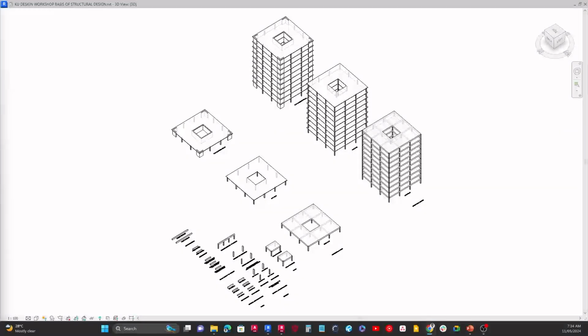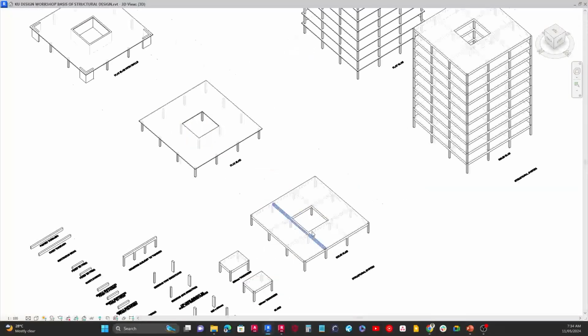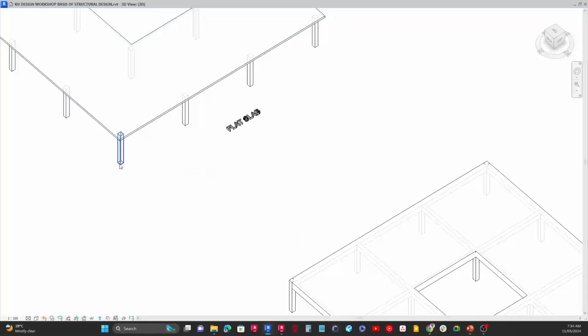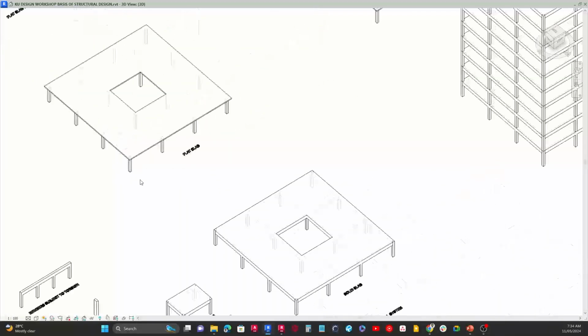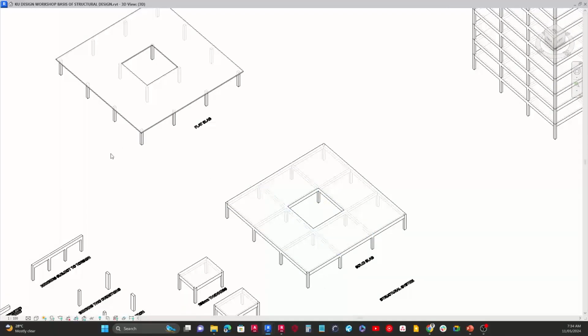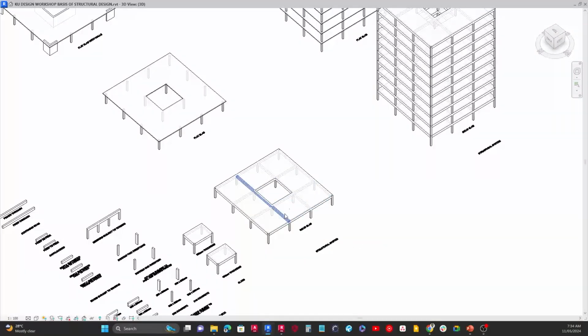That's a good attempt. Definitely the solid slab is going to end up being the heaviest, because when we look at it with the loads of the beams, you can tell which is heaviest based on the axial forces and the reactions at the bottom. I encourage everybody to spend quite a long time on this, especially when we get to looking at full scale building analysis in the software, because it will determine at the end of the day what kind of structural system we end up choosing. So great, thank you so much for that contribution.